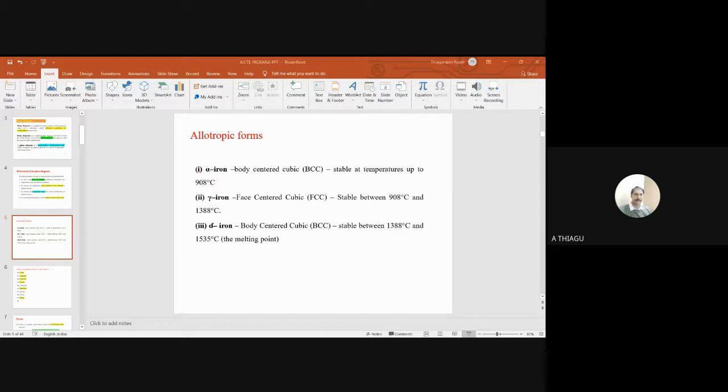So this is the first case I'm going to consider for the transformation of eutectoid steel. We are aware that eutectoid steel has 0.8 percent carbon. The steel should be heated to about 750 degrees and held for a sufficient time, I can take 3 hours. I'm going to hold the specimen at 750 degrees. Then the entire structure of the metal is homogeneous austenite.